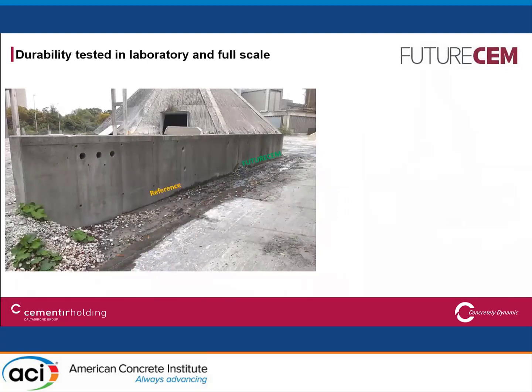And of course, we were looking quite a lot into durability, and I will not say very much about it in this presentation. But I will say that we both did full-scale tests, and we did durability testing in the laboratory. For the laboratory side, the standard testing, we found that the limestone calcined clay cement with this composition had totally comparable durability properties to the conventional Danish concrete, which would be a mixture of OPC and fly ash.